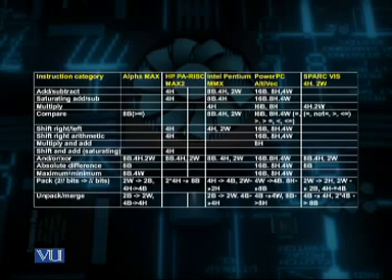You can note from here that narrow operations are shown as of type B, which are performed on byte, of type H, which are performed on half word, of type W, which are performed on word long data, and of type 8B, which is performed on 64-bit or double word data.